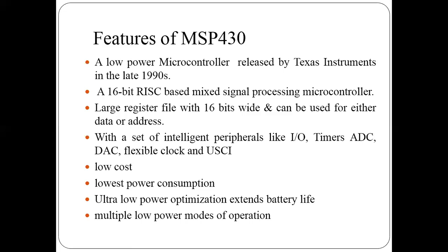Hence, the speed of computation also increases, and it also contains intelligent peripherals like ADC, DMA, watchdog timer, IOs, DAC, a flexible clock system and universal serial communication interface. So these make MSP430 excellent for dealing with various embedded applications, and it is also low cost.